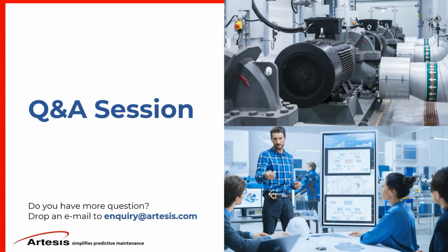Does the system also work on a dynamic system, fast changing flow rates? Yes, this depends how fast the changes are happening. If it's within a matter of, let's say, a couple of seconds, no problem. But if it's quicker than that, it might have a hard time keeping track of real-time changes there.